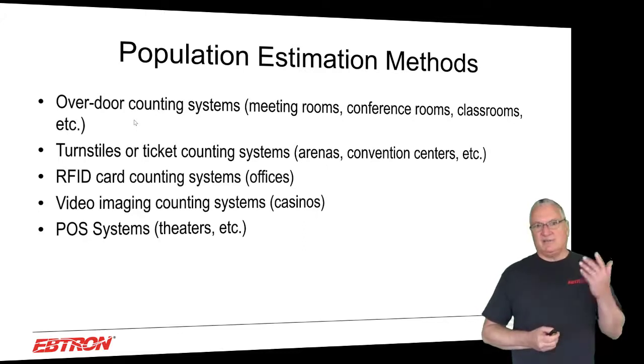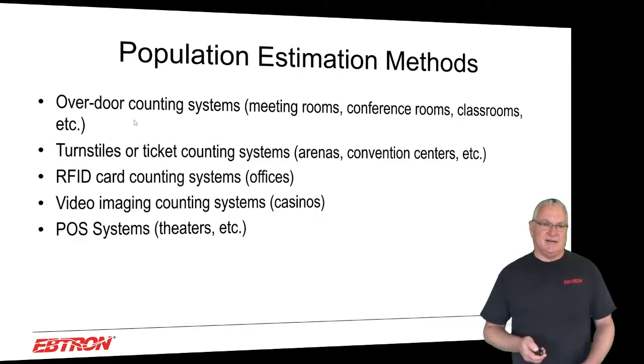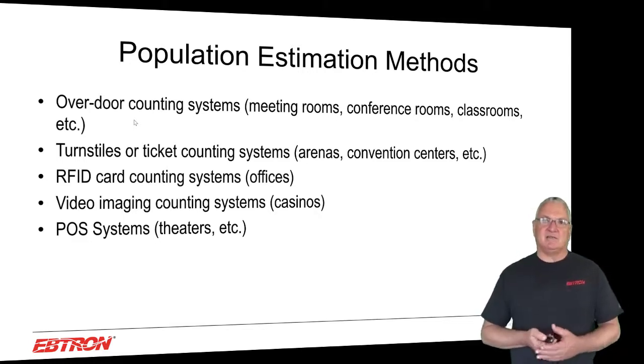The CO2 level doesn't get high enough to do anything until the movie's over and people have left. How's that going to work out for you? Okay, you're totally underventilating the movie theater, all right? And yet you have a point of sale system that tells you how many people are in a theater, when they went in and when they're going to leave. Why aren't you using that?